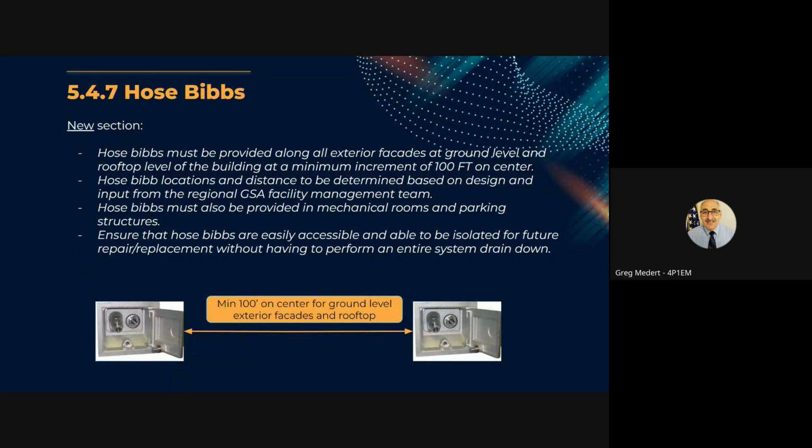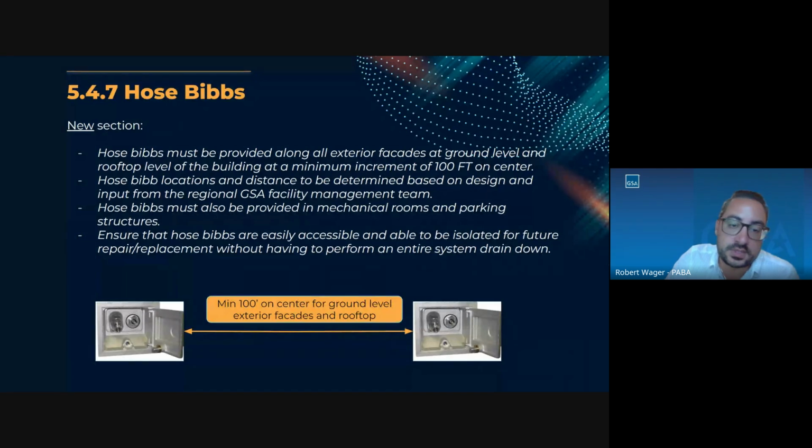I mean, essentially, if it's sourced from the same potable water system, yeah, I guess it's considered a dead end. But the difference is you can open that line and flush it if need be. So I wouldn't really qualify it as a dead end. A dead end is essentially literally just a capped pipe at the end of a riser run that doesn't go anywhere, and it's not allowing for or encouraging circulation of water. If for whatever reason your hose bibs are not connected to a potable source of water, the concern is obviously much less, because it's the potable water system that we're concerned about in terms of maintaining regular circulation.